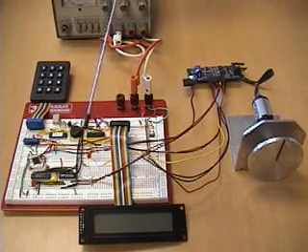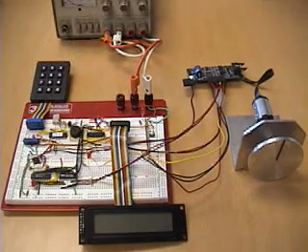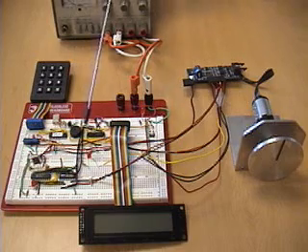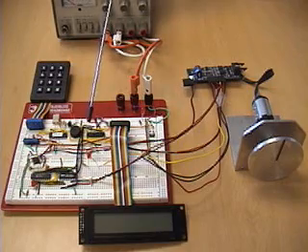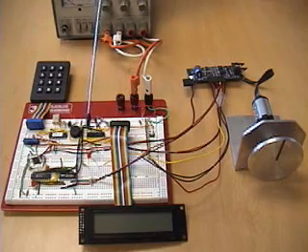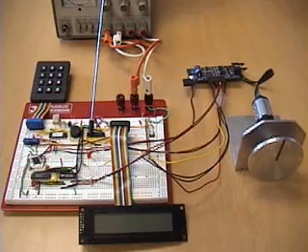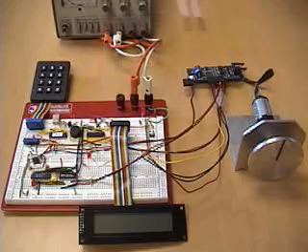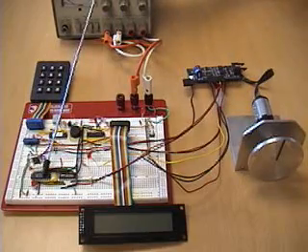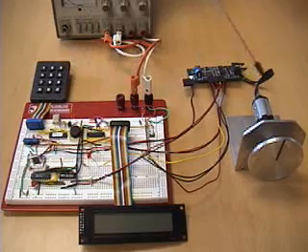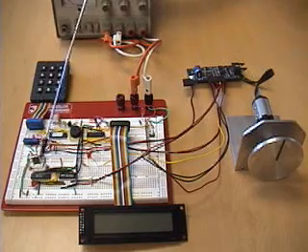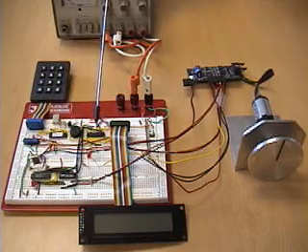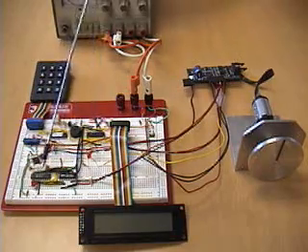Now, let's talk about why we have two microcontrollers here. The main reason is we have a limited number of output ports on one microcontroller. Therefore, we decided to use two, one of which is the master controller, or the main controller, that controls the DC motor. The second microcontroller, the F84, provides input data from the encoder and then transmits that data to the main microcontroller using a serial interface between